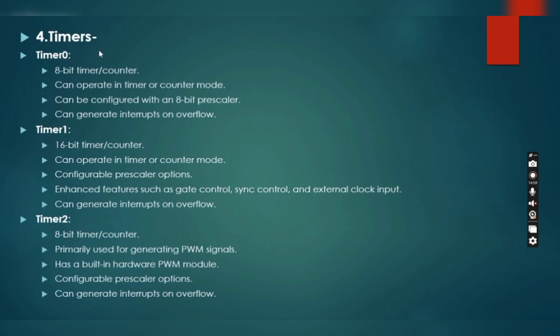Timers. We have used Timer 2 in this project, but the PIC16F877A has three different timers: 0, 1 and 2. We can use these timers for various important purposes. So far we have used a delay procedure to implement some delay in the program, which was counting up to a specific value before the program could continue.